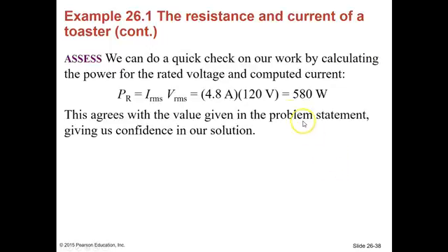We do a quick check on our work. We can calculate the power for the rated voltage, so 4.8 amps times that 120 volts does give us 580 watts. So that agrees with the value in the problem, and yay, we're happy with our solution.